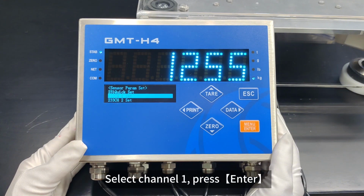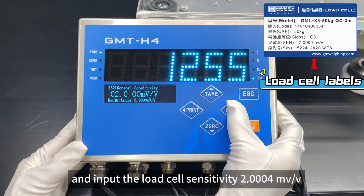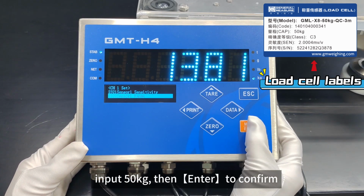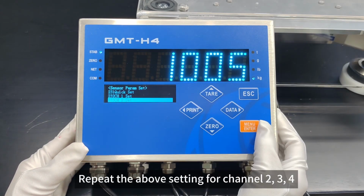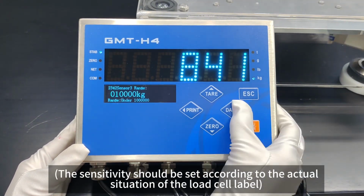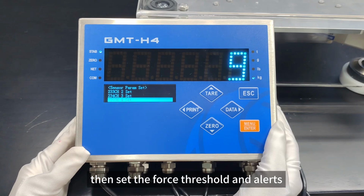Select channel 1, press Enter, and input the load cell sensitivity 2.004 millivolts per volt. Then press Enter to confirm. Select weight range of channel 1, input 50 kilograms, then Enter to confirm. Repeat the above setting for channel 2, 3, 4. The sensitivity should be set according to the actual load cell label. Complete the setting, then set the force threshold and alerts.